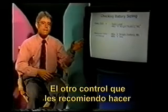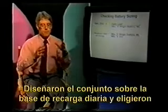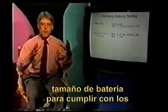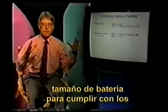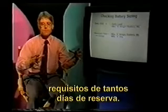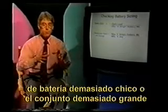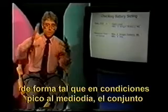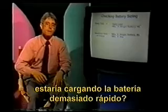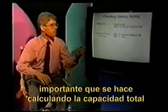The other check calculation that I'd recommend you do is to check for the maximum rate of charge. You've designed an array, you've chosen a battery size. You've designed the array based on daily recharging, and you've sized the battery based on meeting certain days of reserve requirements. The question is, how do the two match up? Have you designed the battery bank too small or the array too big so that under peak conditions during the middle of the day, the array would be charging the battery too quickly? Typically in photovoltaics, this never occurs as a problem, but it's an important check.